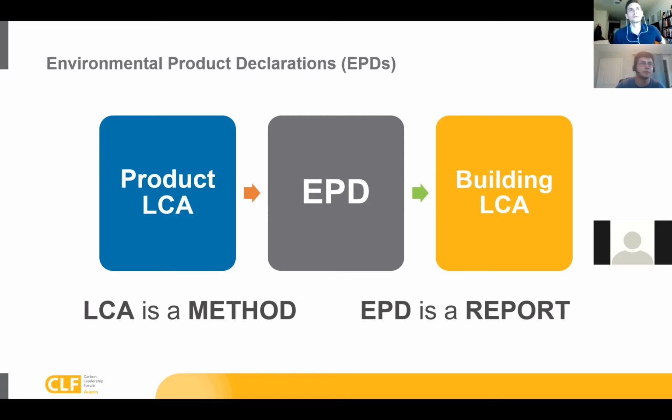Right. So in Tally you will identify a ceiling tile, and the impact of that ceiling tile will come from an LCA that was done on their module A essentially, and the EPD that came from it. So we'll know, essentially from cradle to when it gets to the construction site, what the impacts have been of that thing in your building, whatever that is. And these tools, Athena and Tally and others, can help amass those and give you an idea. So then you can actually run an LCA on your whole building.